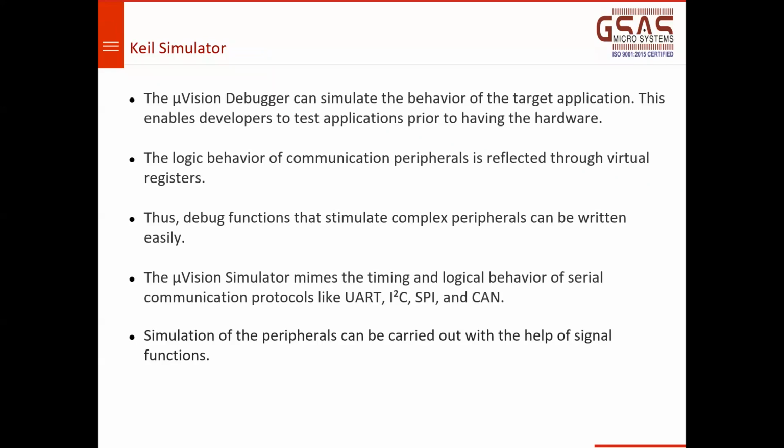Okay, so to access the microcontroller pins, to give input to the microcontroller pins, or to send output to them, Keil has given a feature called virtual registers. And as the name suggests, virtual means these registers are not part of the processor, they're not part of the MCU, but these registers are specifically given for simulation purposes.